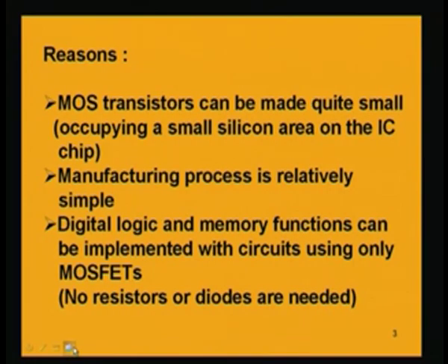Another reason for the growing use of the MOSFET is that its manufacturing process is also simple. And another important factor is that digital logic and memory functions can be implemented with circuits using only MOSFETs, and no resistors or diodes are needed.